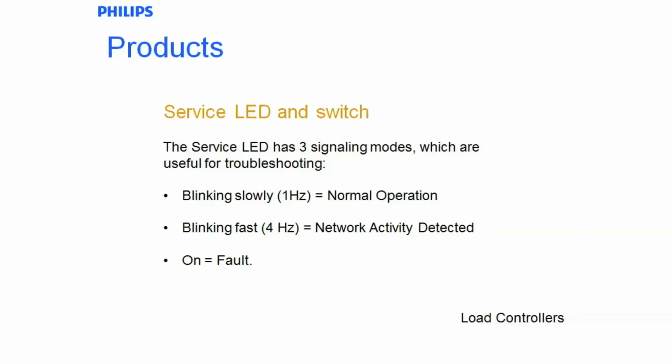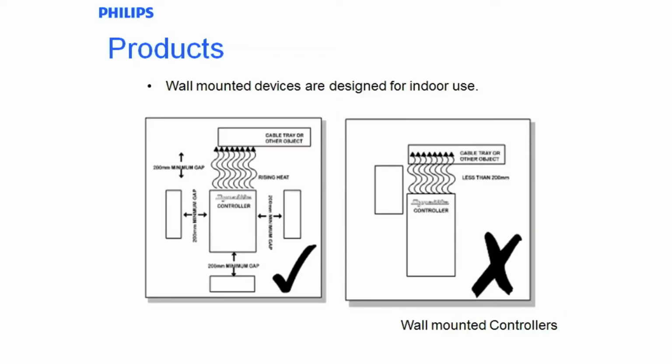It is fully programmable within the controller, so you can program it to do various tasks. Most importantly, make sure the cable length between this input is no longer than 2 meters and make sure you keep it clear of any mains cabling. This will go straight into the microcontroller port, so it's very prone to noise pickup. This is particularly applicable when we are talking about any of our dimming products. Not so much with our contactor or ballast control products.